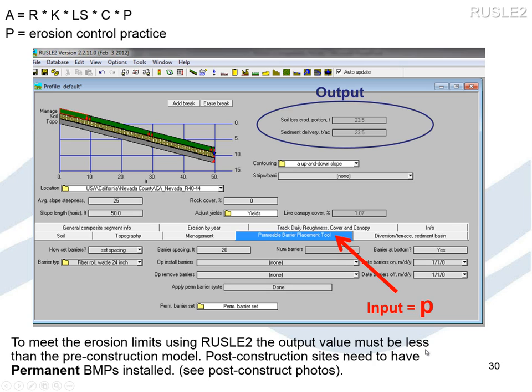Again, sediment controls are measures that are going to capture sediment as it's dislodged. One thing the regional boards look out for: if you place complete reliance on sediment controls, that's probably not the best strategy in the world. I think most of the regional boards are looking for good erosion controls to be in place before they're going to sign off on a project. So the P factor is something in many cases we're going to want to use to minimize the sediment delivery off-site, but placing complete reliance on that P factor is kind of risky business. So just a caution to put out there.